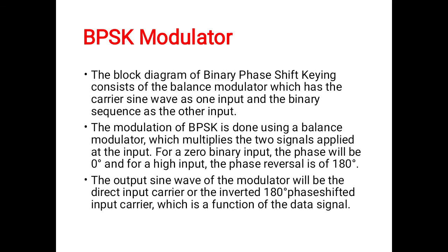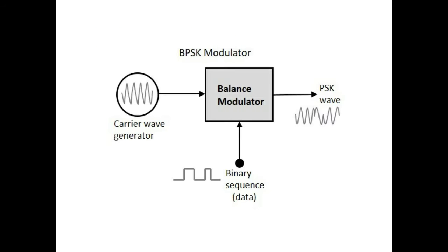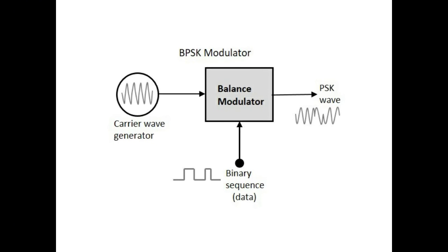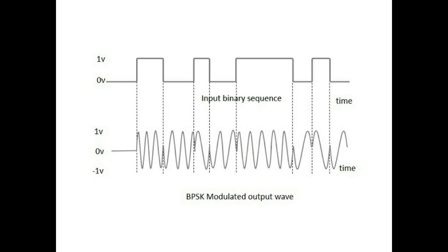Now, BPSK modulator. The block diagram of BPSK consists of a balanced modulator, which has the carrier sine wave as one input and the binary sequence as another input.